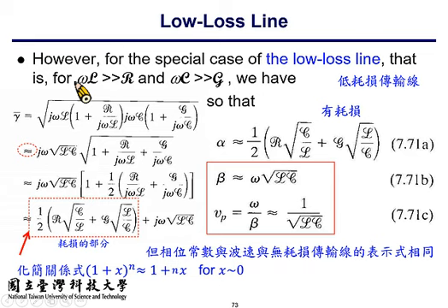If R and G are relatively large or cannot be neglected, this is a complex number. Which means what? If this is a complex number, what is the significance? What is the implication of this result? Then this result suggests the voltage and the current are not in phase at the specific point of the transmission line.